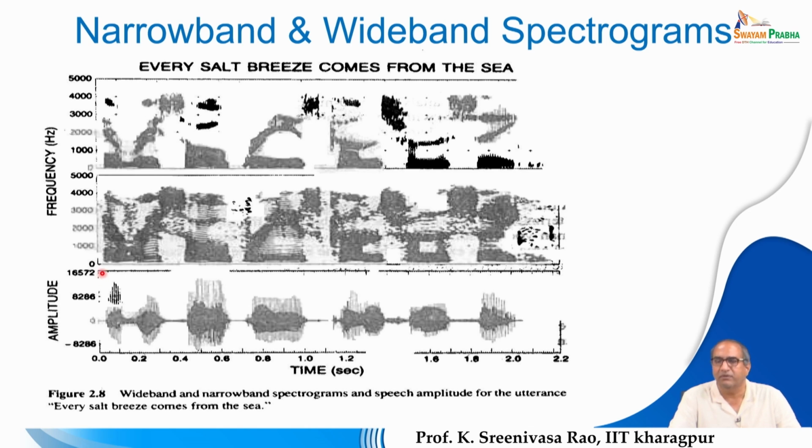For every frame, when I compute the Fourier transform, I get a list of frequencies, and for every frequency the strength or energy it possesses; all that information I can find. The spectrogram is stacking all this spectral information in a consecutive way. In the spectrogram you can observe there are three types of information. We compute the spectrum for every frame, and then we stack those spectra with time alignment to the time domain signal.